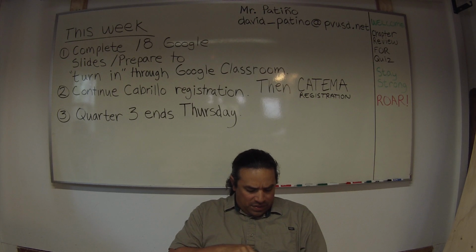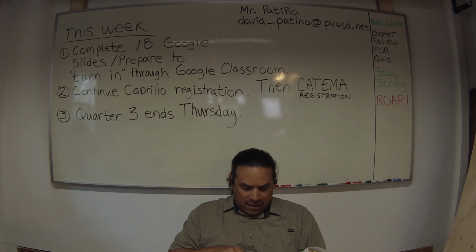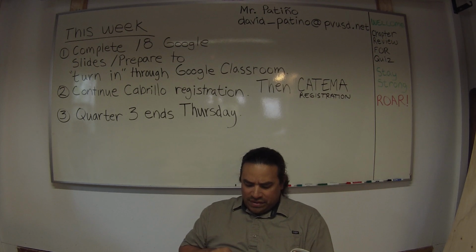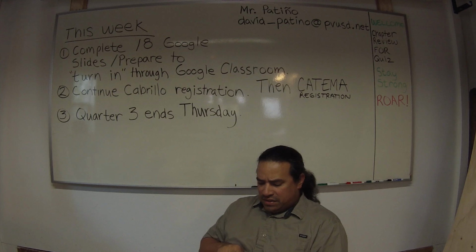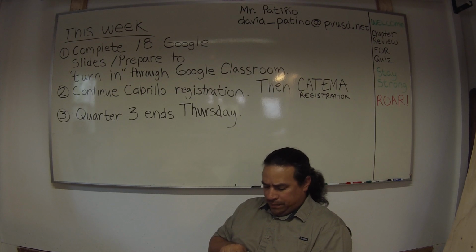A number of hardwoods have large pores in the cellular structure and are called open grain woods. They require additional operations during finishing. Different kinds of wood will also vary in weight, strength, workability, color, texture, grain pattern, and odor. Study the full color wood sample at the end of this unit as a first step in wood identification.